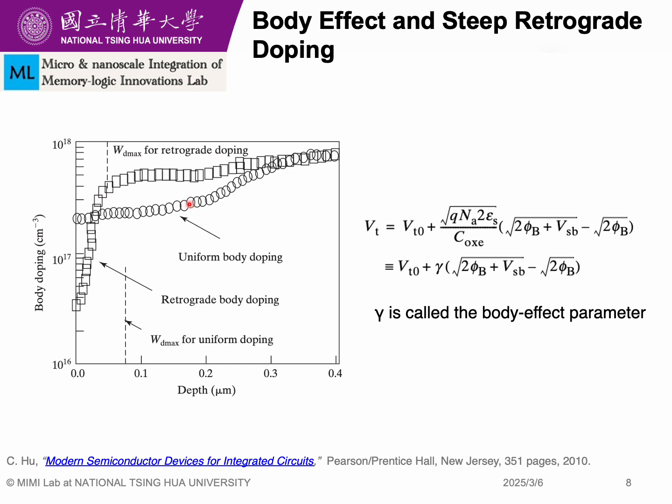In that case, the theory for the body effect is more complicated, where this Vt can be obtained by replacing the phi 2b term with phi 2b plus source to bulk voltage, and therefore this gamma is called the body effect parameter, and Vt is not a linear function in the equation. So sometimes we can do a Taylor expansion to linearize this.